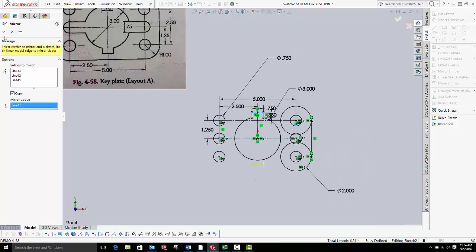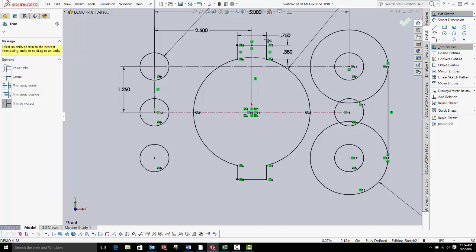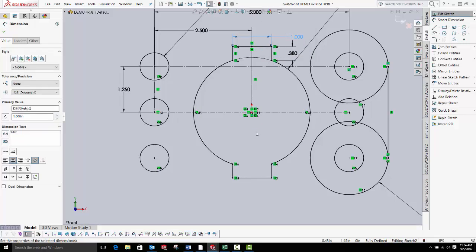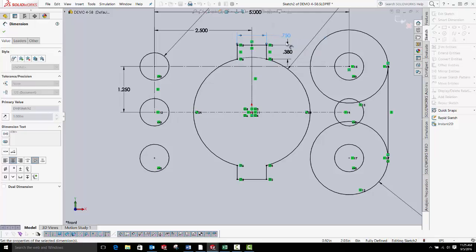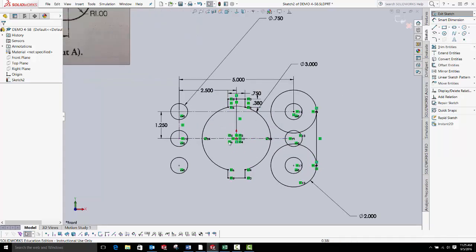We're going to choose this one and hit the check mark, and you have a fully defined sketch that comes down because this one is defined. Whatever changes we make to this also happen on the bottom. They're connected. They have a symmetric relationship. That's what this icon is. Notice the orange point at the top matches the pink and orange square at the bottom down here. And that's our design intent, right? We want those to be equal all the time. So briefly, that's our mirror command.